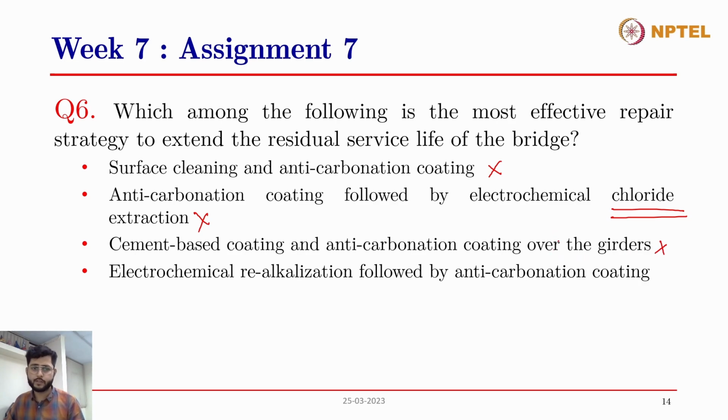And the fourth option is electrochemical realkalization, followed by anti-carbonation coating. Yes, first we need to realkalize the concrete. The pH must have gone down, and therefore we have to implement this technique, the ERA technique, for the pH to be enhanced inside the concrete, so that the concrete will have a conducive environment for the steel reinforcement.